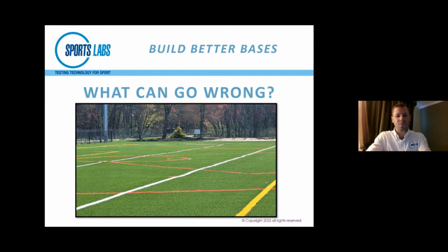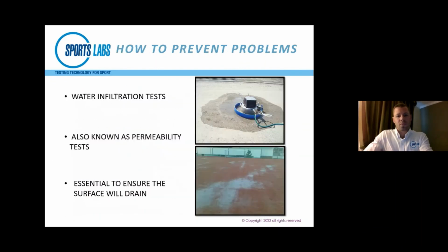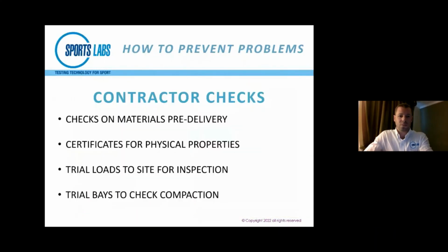You'd have a set of tests taken on the subgrade materials, and then there would be a key stage inspection for subbase, which might involve, even as it's being laid, you being in to sample the material to check that the gradation and the physical properties are as per the specification. And then obviously when the subbase is finished, there's a number of tests we can do at sign off, so we can do the porosity, compaction test, the planarity, stuff like that.